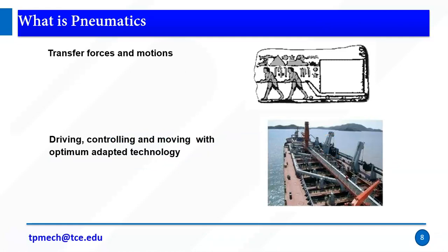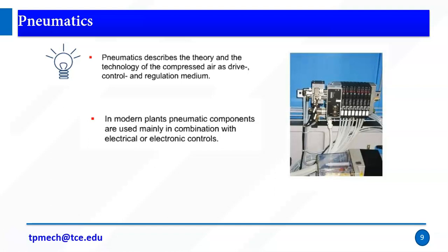Fluid power transfers forces and motions. Pneumatics transfers forces and motions, driving, controlling and moving with optimum adapter technologies. Adapter technologies means we cannot use pneumatics in all situations. It doesn't meet all the requirements because of the compressibility factor. Pneumatics describes the theory and technology of compressed air as a drive, control and regulation medium.